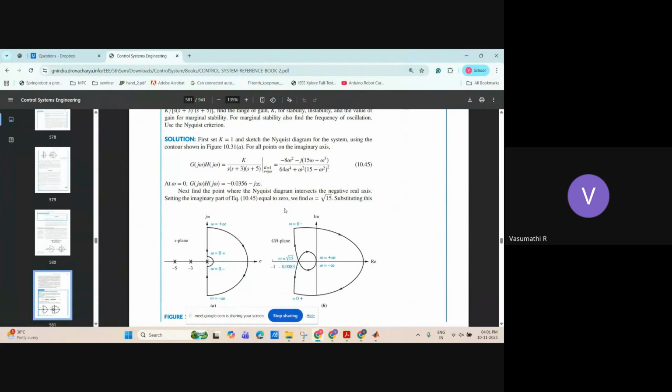Yeah, so it comes through the root locus. See, we don't need 0.3 also. -0.3 would work. So I have an open loop zero in the right half of the S plane, s equal to 0.3 I have taken.